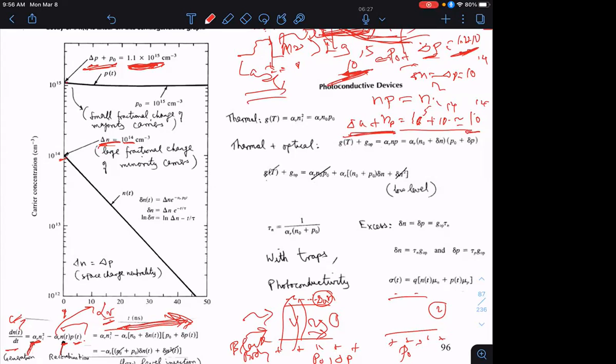Now, assuming there's no laser light shining on it, this black body absorption and recombination process is what establishes this N sub i. Remember that? This intrinsic carrier concentration is because of this dynamic equilibrium that you have with the surrounding environment. Okay, and that's what establishes N sub i, the intrinsic carrier concentration. And that's going to happen regardless of whether I'm shining a laser or not. Now, if I didn't shine the laser, this semiconductor was just sitting there and had a carrier concentration N sub i.